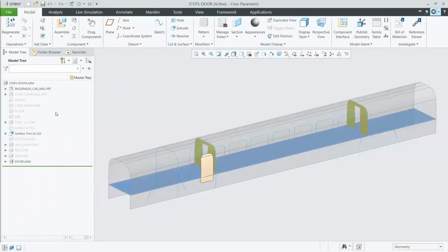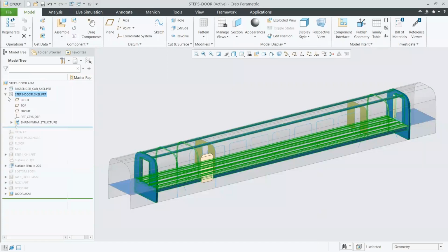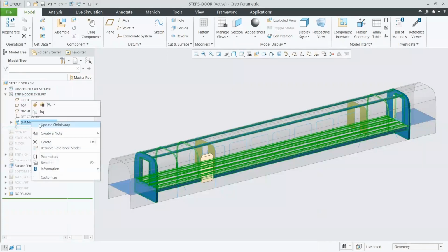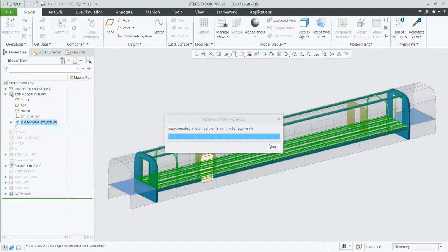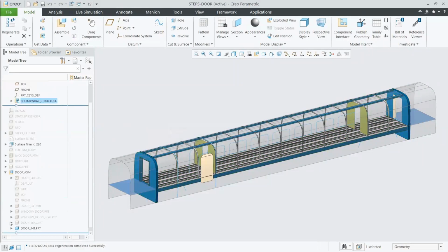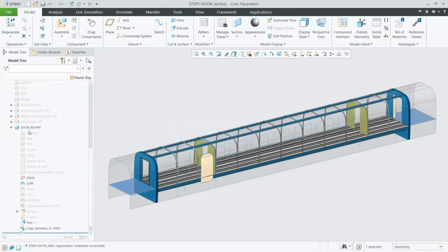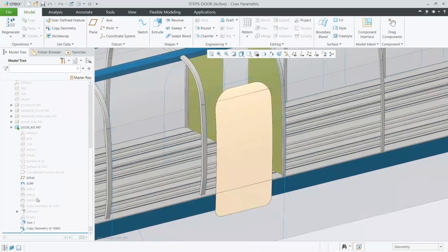And now we can go ahead and start working on the doors. And it's really the same sort of thing. I've got my skeleton model here inside of my door assembly. In this case, I also have a shrink wrap of the rest of the geometry. I need to work on the door and I want to be able to see the rest of the piece, but I don't necessarily need to work with the entire cart assembly. And it's very easy to work around things like that shrink wrap of the model.